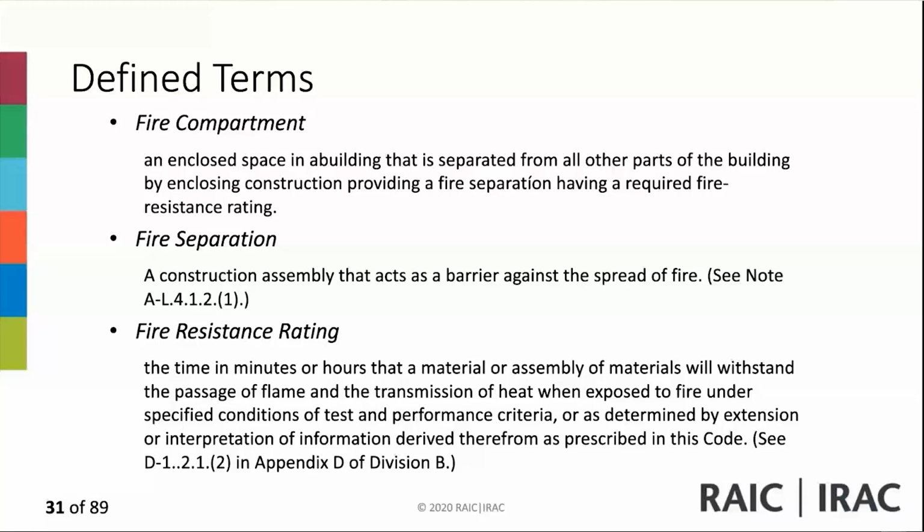It's a 2-hour fire resistance. Does it say that this is a 2-hour fire resistance under different conditions in real life? No, but if you test it to this test, this is the minimum requirement and performance we want out of it. Now in Appendix D, you're going to see different fire resistance ratings.